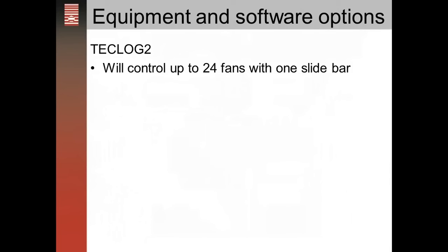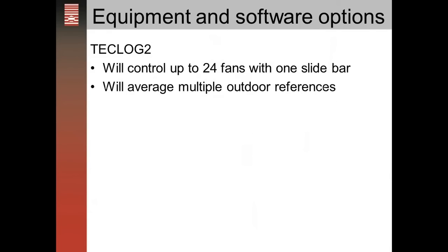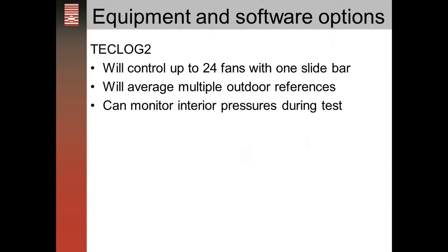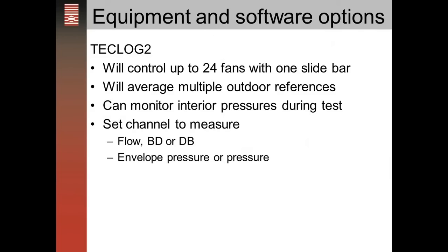Techlog II is designed for data logging pressures over a long period of time. You could use it for CAS testing. And it is designed where you can control up to 24 fans with one slide bar. It will average multiple outdoor references and can monitor interior pressures during the test. So lots of functionality, lots of options.